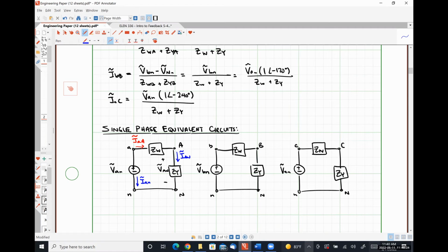Okay, rather, so we can't calculate the voltage uppercase A? We could, but that would just be the voltage drop across our transmission line, which usually isn't something that we're particularly interested in. So that's not our line voltage? No, our line voltage would be V uppercase A to V uppercase B, right?